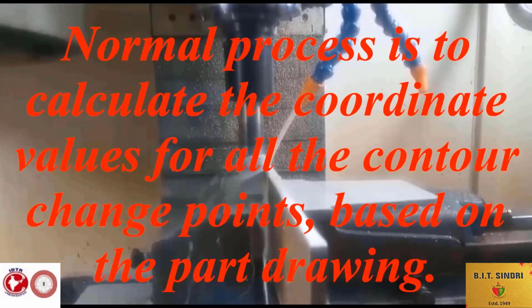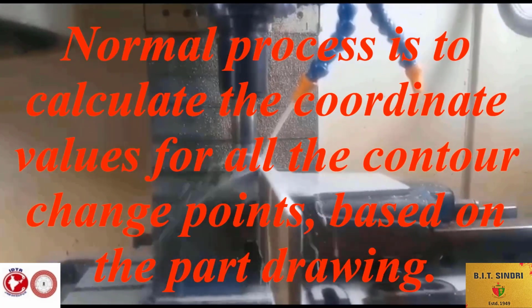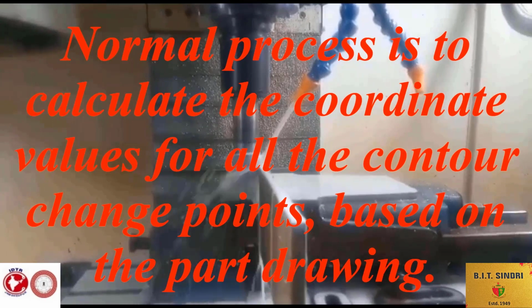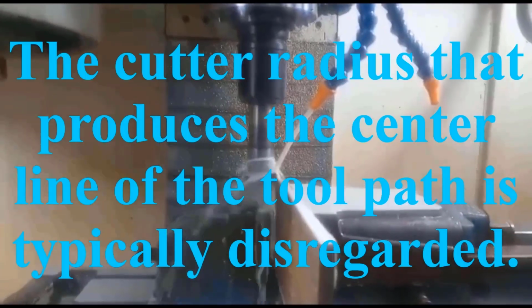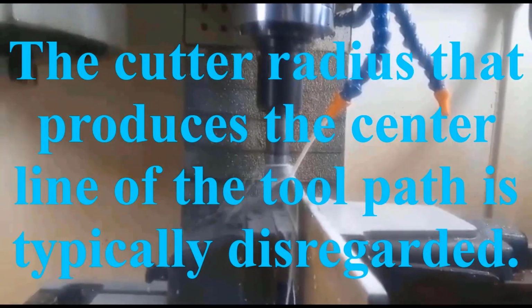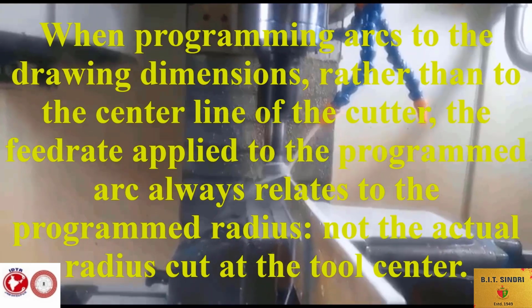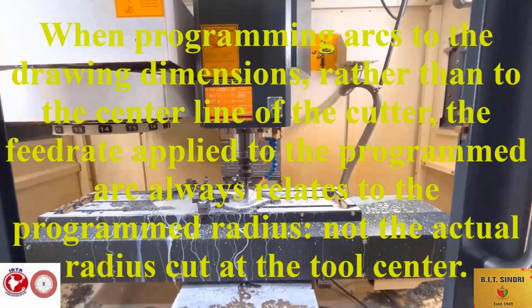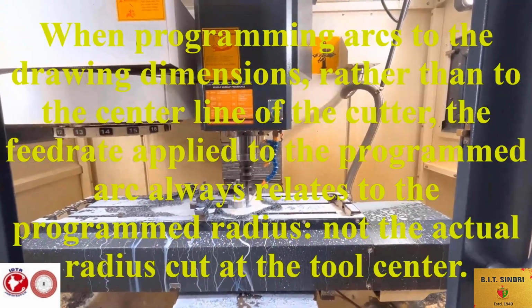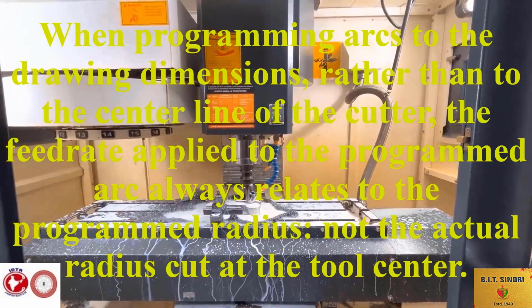In programming, the normal process is to calculate the coordinate values for all the contour change points. Based on the part drawing, the cutter radius that produces the center line of the tool path is typically disregarded. When programming arcs to the drawing dimensions rather than to the center line of the cutter, the feed rate applied to the programmed arc always relates to the programmed radius, not the actual radius cut at the tool center.